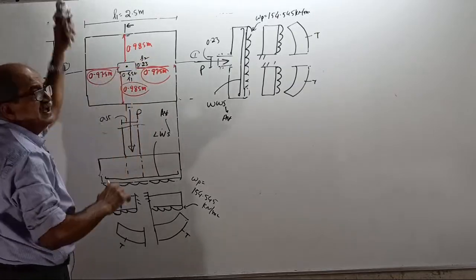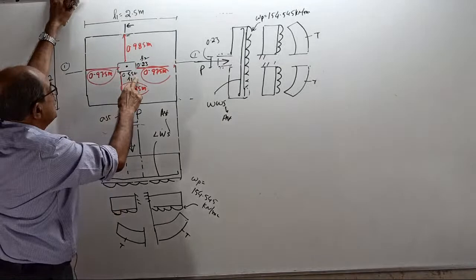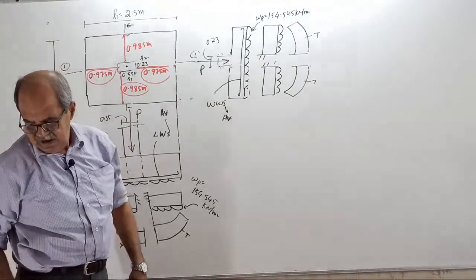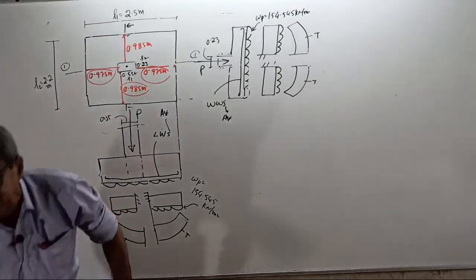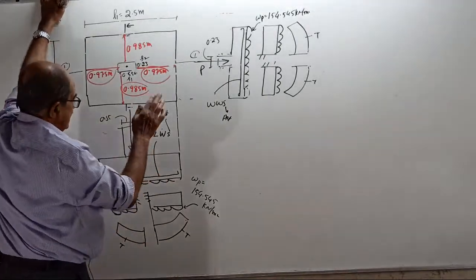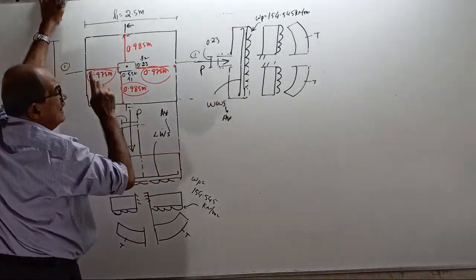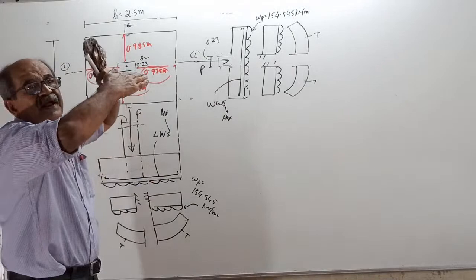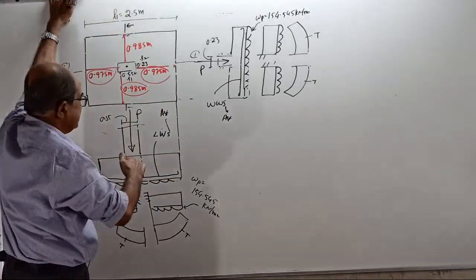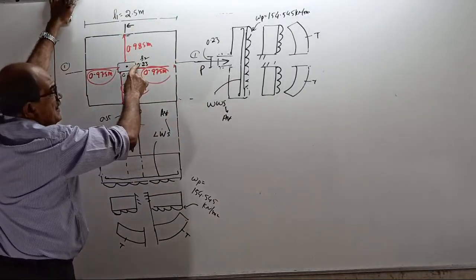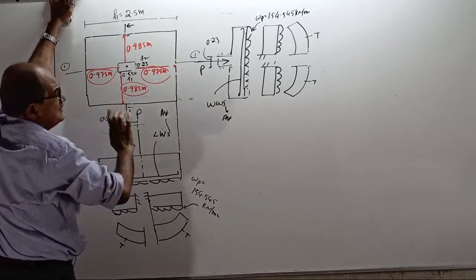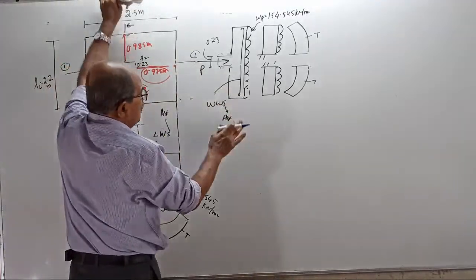In the procedure, you should not write 0.55, 0.23; nothing to be written in the procedure. Okay, then write both the sketches here. Write the design principle: designed as a cantilever, fixed at the face of the column and free at the edges. Okay, now start one by one.